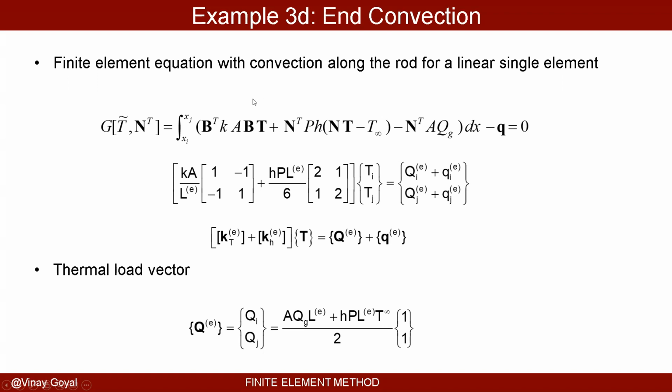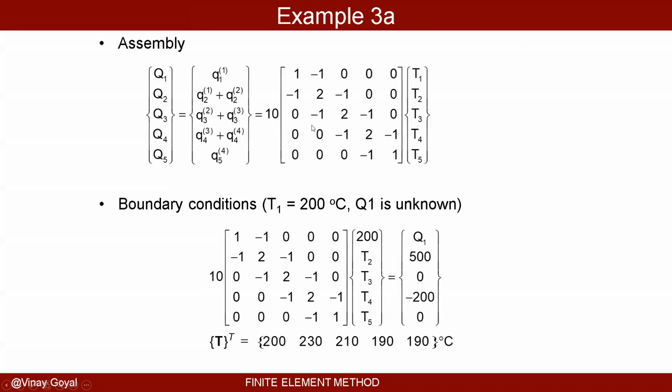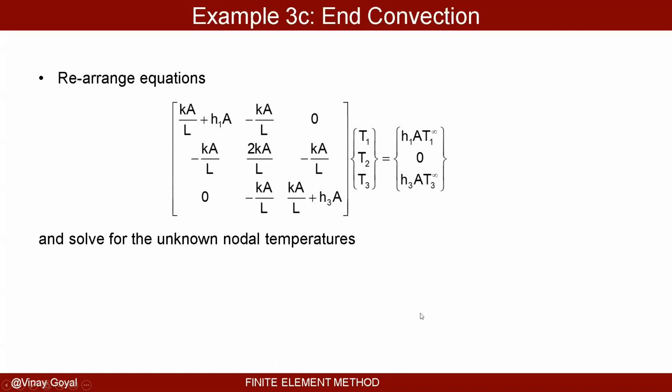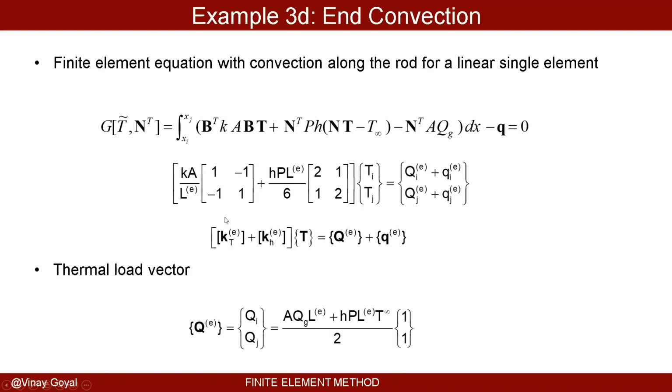We already did this, by the way. This equation here was derived from first principles, and we arrived at this weak form. I'm just repeating that equation here to remind you. And when you do the integrals for a linear element, and I encourage you to do that, you get this simple set of equations here. K, A, L, all these are known. And these are your distributed loads, this Q here. Q are the point heat fluxes. And when I say load, I mean heat load.